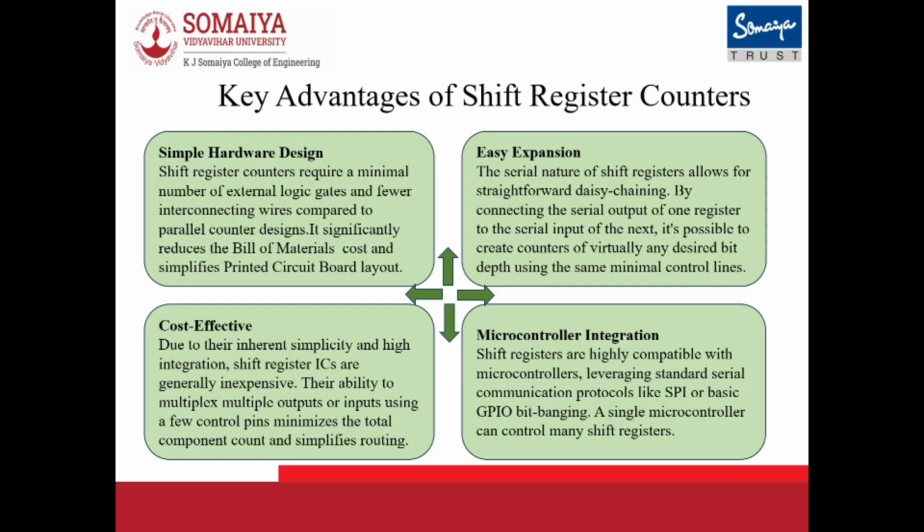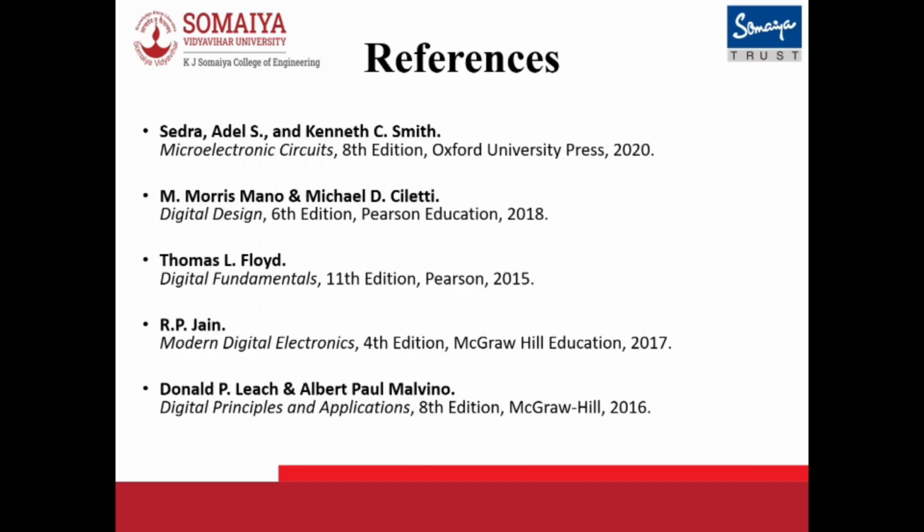Third, microcontroller compatibility. They can easily be controlled using standard serial protocols like SPI. Fourth, easy expansion. Multiple registers can be daisy-chained to extend bit length with minimal wiring. These features make shift register counters one of the most scalable and designer-friendly components in digital electronics.